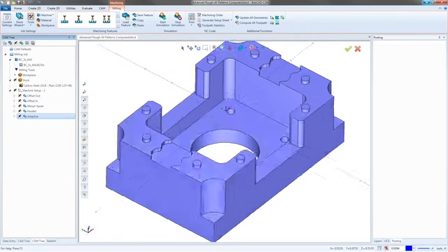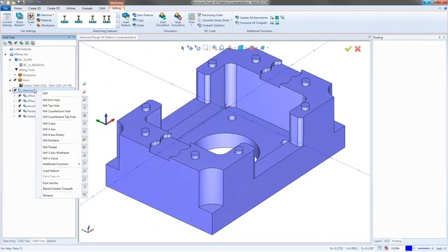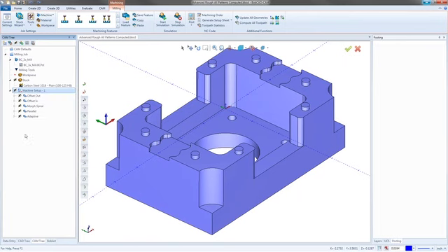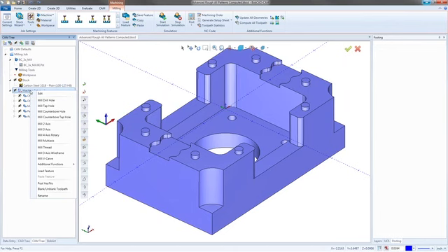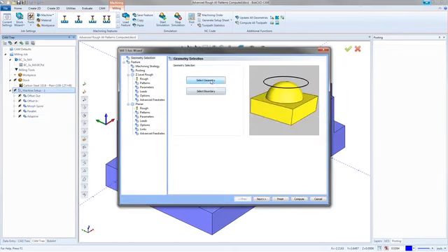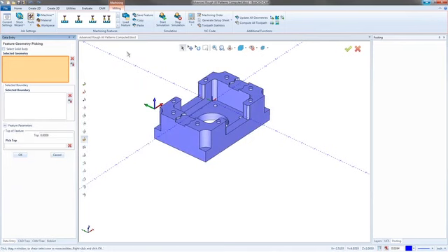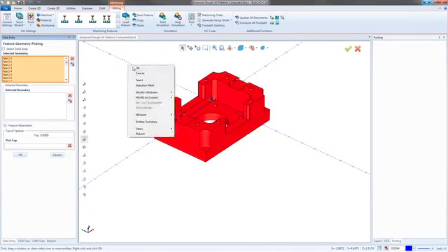So in here, I have a bunch of toolpaths. I'm going to start off by actually creating a toolpath, and then I'm going to show you guys each individual option for that toolpath. So advanced rough right here, I'm just going to right click on my machine setup 1 and go down to the mill 3-axis. Now, remember, when you pick your geometry, you're always picking the entire part. So I'm going to drag a box over the whole part and then right click and hit OK.